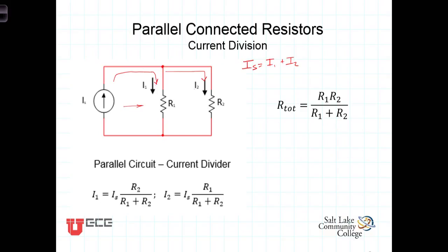For example, if we let R1 equal 10 kiloohms and R2 be 1 kiloohm, the parallel equivalent, or the total resistance seen by the source pushing at them, will be R1 10K times 1K divided by 10K plus 1K. And that gives us 10 divided by 11, or 0.909 kiloohms, which is equal to 909 ohms.